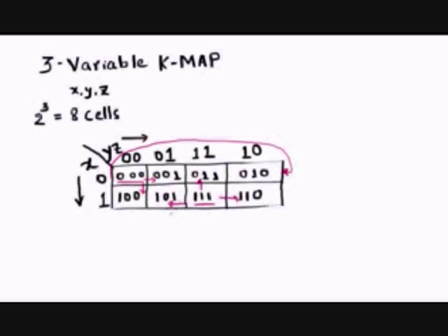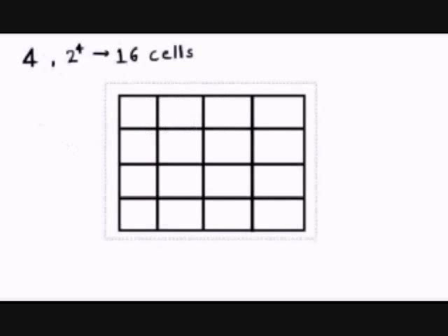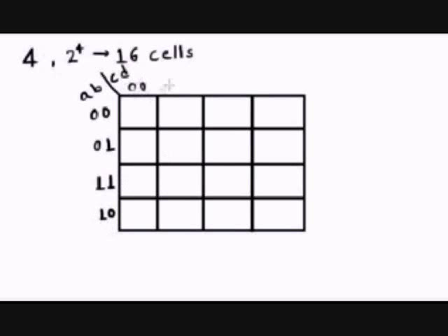This was with respect to the construction of a 3 variable Karnaugh map. Now we'll consider how to construct a 4 variable Karnaugh map. Here we'll have 16 different cells. Let me extract a Karnaugh map that I have drawn with 16 different cells. I let AB vary this way and CD vary that way, and AB will take value 0,0, 0,1. Again we may tend to write 1,0, but it has to be 1,1 and then 1,0. The same applies with CD also, and again it cannot be 1,0, it has to be 1,1 and next 1,0.